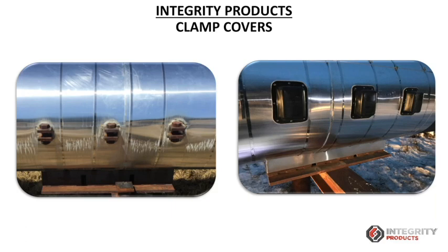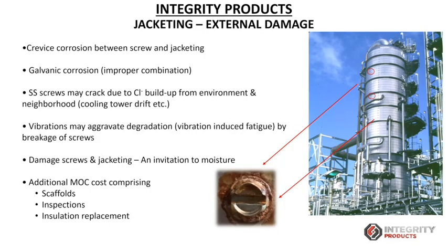We might have seen that we have to build metal boxes by cutting the jacketing. There is time required for that, and a workmanship cost. This can easily replace that. It's quick and easy to install, and because of its flexible design, it can fit different corners and different shape profiles. So now we have spoken about corrosion damage to the metals and to the insulation.